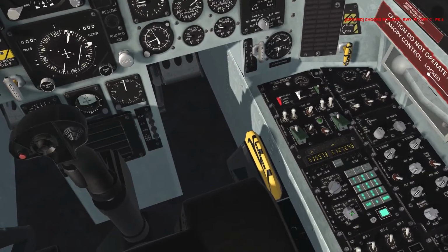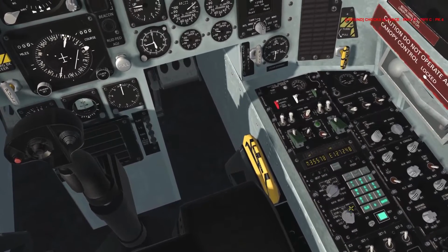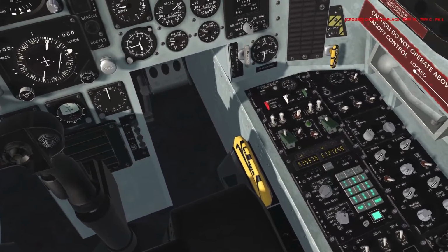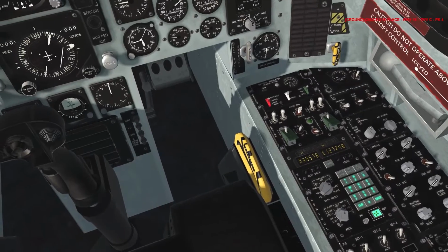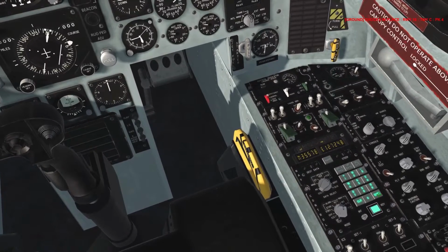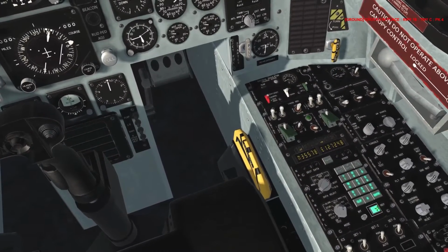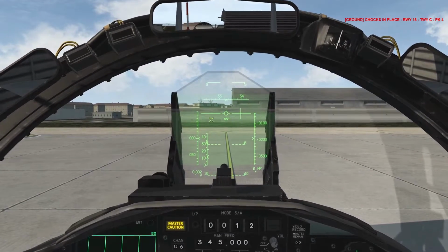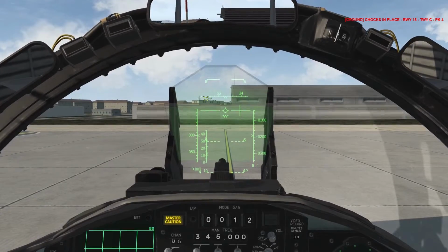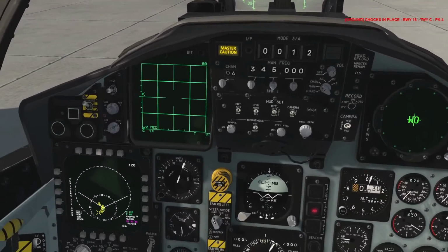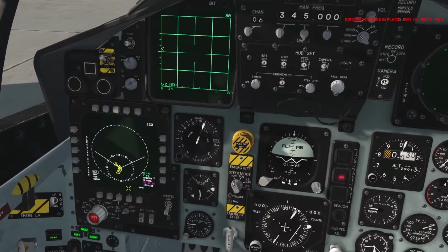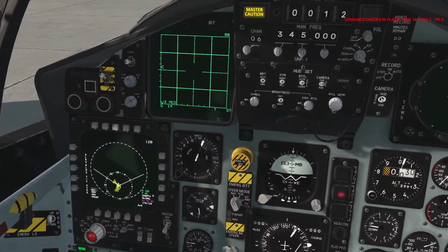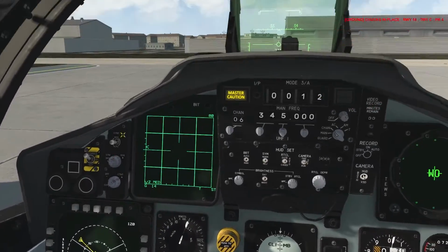So we can select the mode knob to INS. The light goes out. Numpad, press ready, verify NCI lights on. Well, the lights are still on, so we can press enter to confirm the alignment. And then press ready, verify NCI lights out. And you can just observe that you've got good data in the HUD and on the VSD, the situation display as well. You got your flight plan looking somewhat as it should.